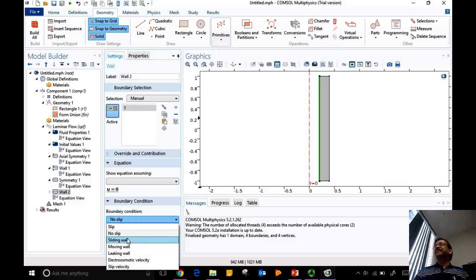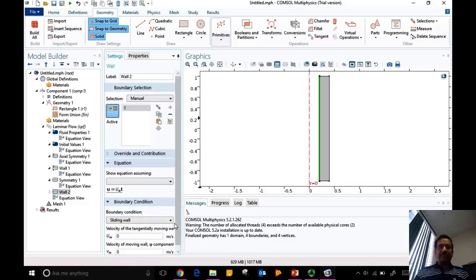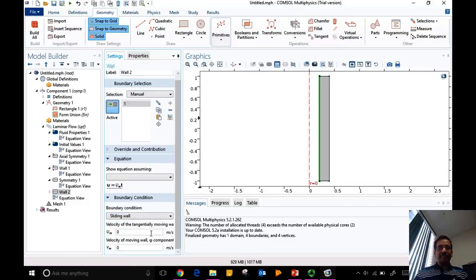What is the slip velocity? Slip velocity you need to pick and specify. So, I actually have a question. Yeah, there is a threshold over which the fluid would actually slip over this, which you can only find out through computation sometimes. Would slip over the wall if it's too fast. As long as the Knudsen number criterion is satisfied, that means there are enough molecules between collision, you will not have a slip condition. Okay, so the slip condition occurs under extremely rarefied gas.